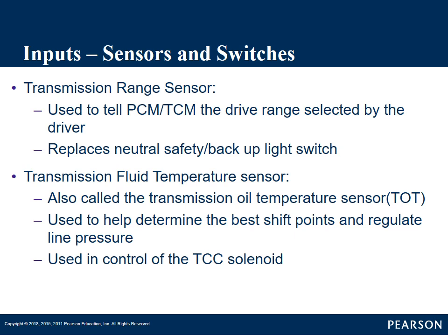What it does is, if I put it in low gear, then it'll limit the upshift of that transmission, because we're telling the transmission, I want to be in low gear. Now, in many electronic transmissions, if you rev it up high enough, there's a program in the control module that will go ahead and shift to save the engine from damage from over revving.